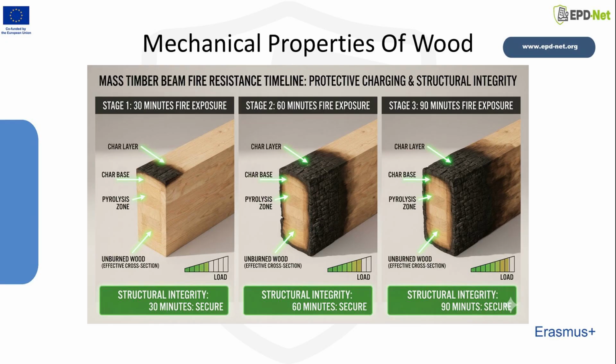Resistance properties refer to the behavior of wood when the elastic limit is exceeded. Compressive strength is high parallel to the fibers and much lower perpendicular to them. Tensile strength provides the highest strength value of wood when applied parallel to the fibers. Bending strength combines compression, tension, and shear effects. Shear and splitting resistance are especially important for joints, nails, screws, and structural detailing.